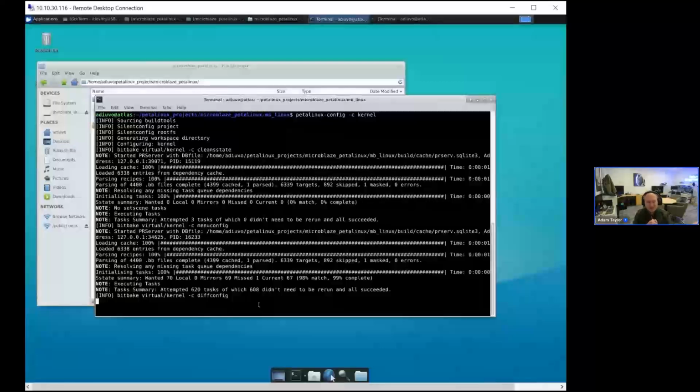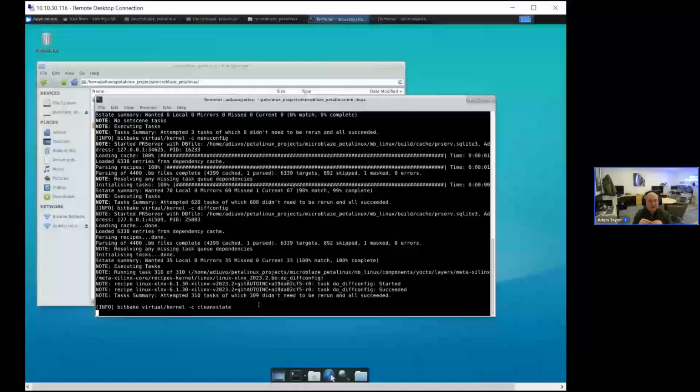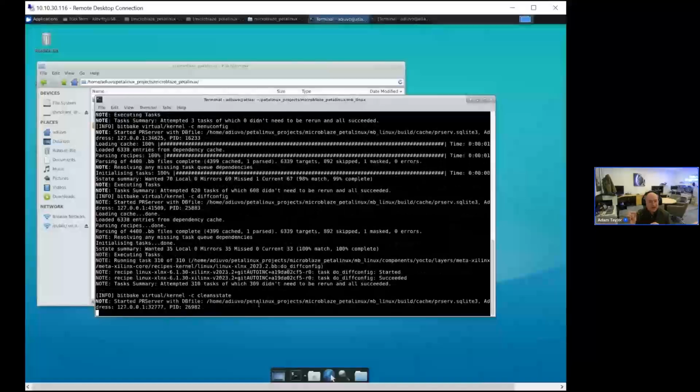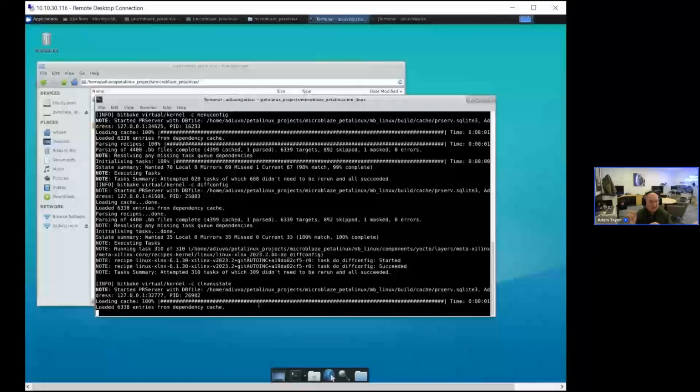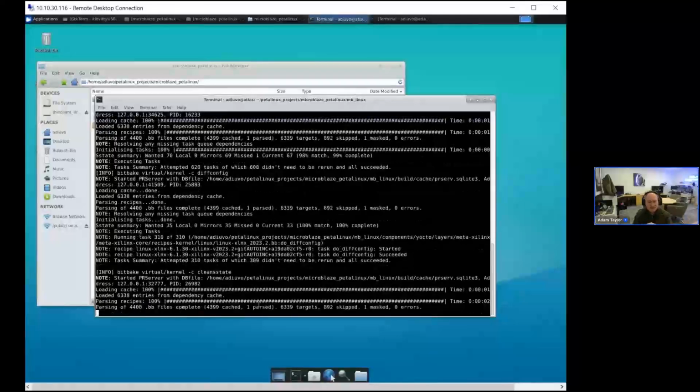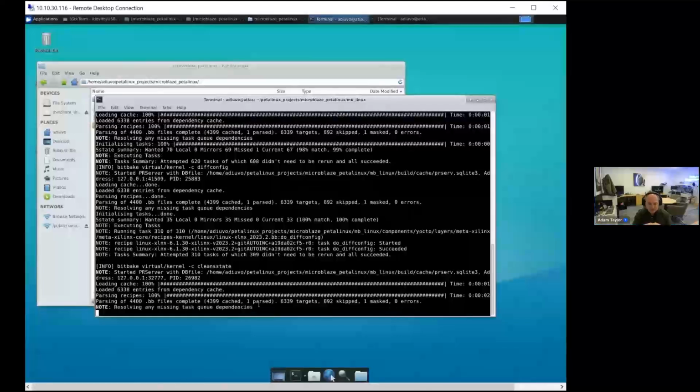So the thing is, this gives you the entirety of what's in there for SPI and for all the different flavors of Linux, because Linux supports lots of different things. By default, the Xilinx ones are in: when you load that XSA in, it enables the one that you need. The user mode ones are there because I knew that there was a thing called spidev that I wanted to use, and it's not enabled by default. Then I Googled it, and it said, hey, you need to enable these user elements in the file there.